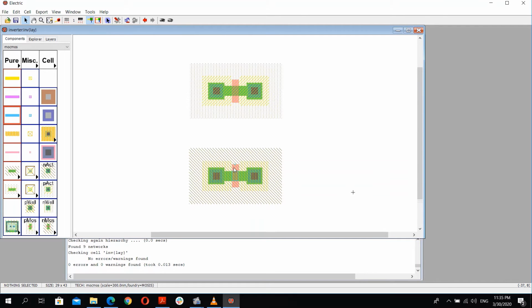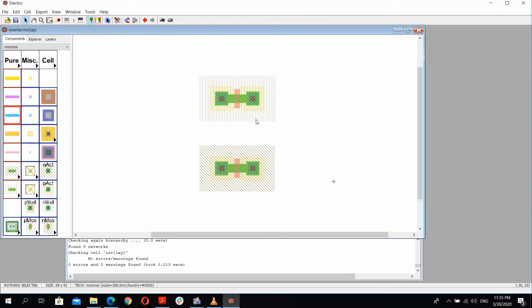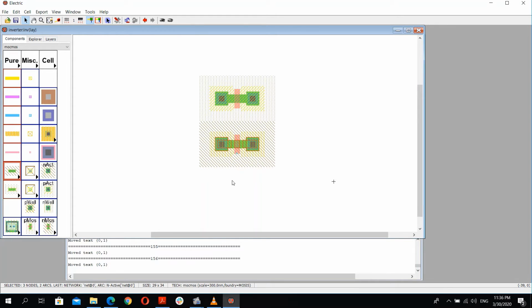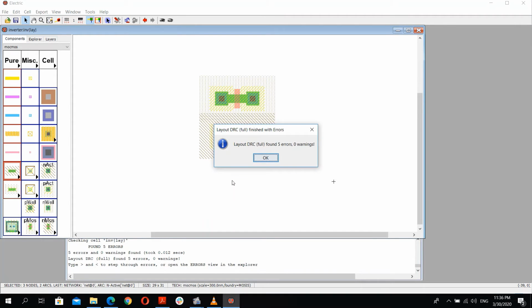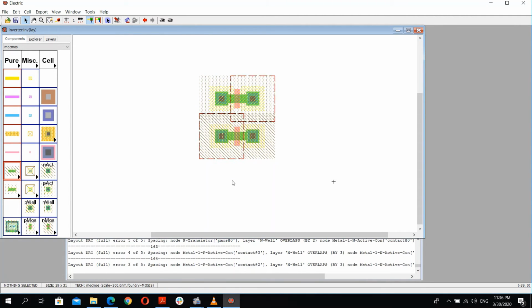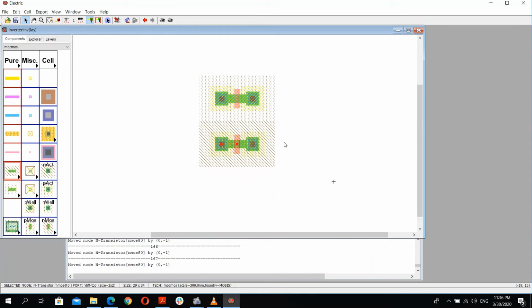Okay, so we connect the inputs and the outputs. As you know, the inverter here, we try to get this closer and closer to the other one because when you are making a standard cell library, it's better to have a lower height for all the cells. So we try our best to make this compact, as lower height indicates that we could better use our space. So we make it until we don't see a DRC. I think it happens when these areas are not intersecting.